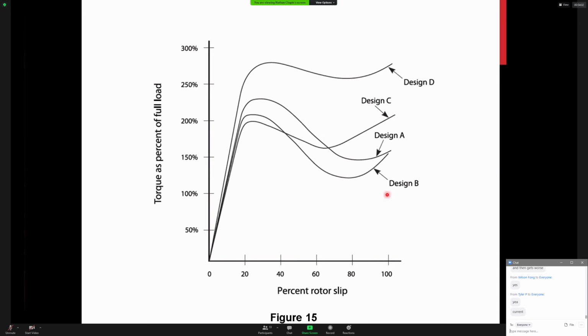So there are 4 different NEMA rotor designs, which I've mentioned a few times now. We have NEMA design A, B, C, and D. Actually, there's a NEMA design E as well. But what you can think of is design A and B, those are your general purpose motors. So even though we're going to control the torque and everything with a variable frequency drive, the design of the rotor must also be selected appropriately. So A and B are general purpose.